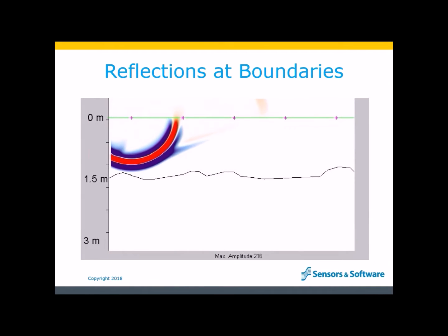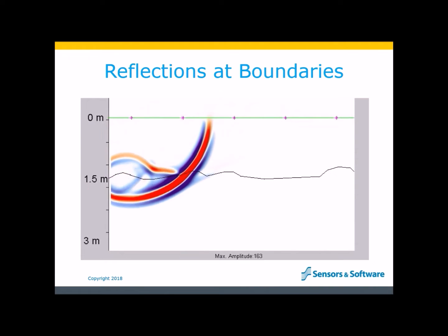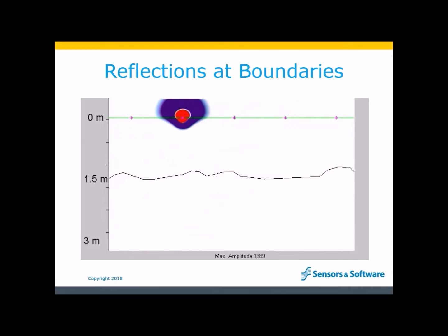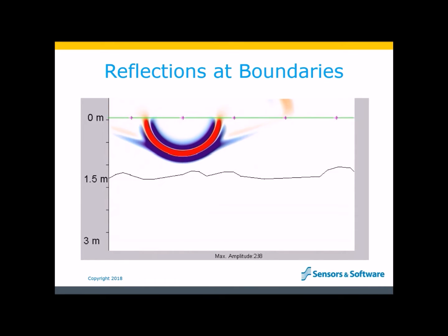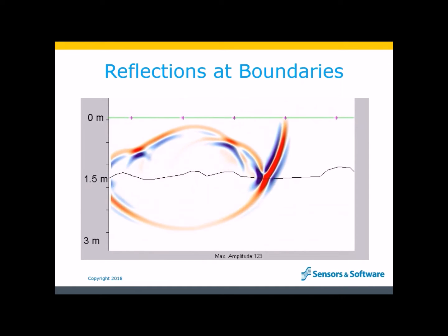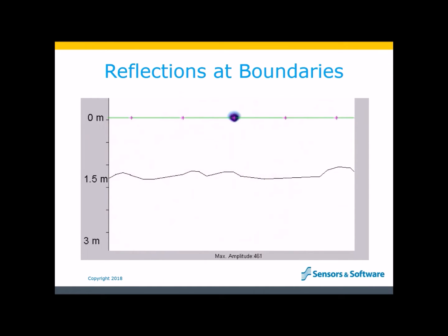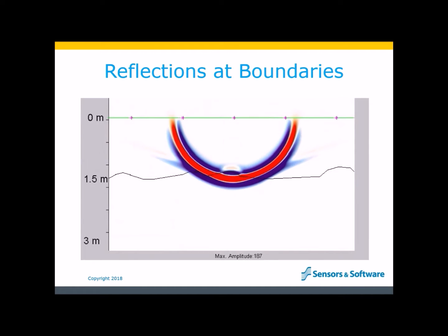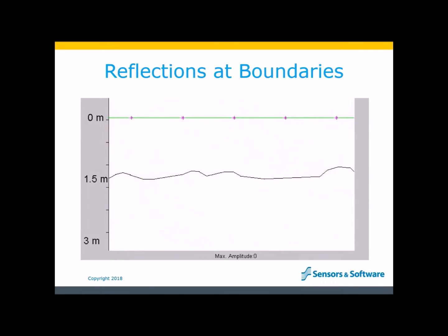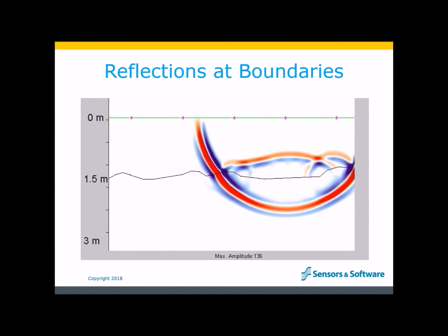Here's another animation that shows the concept of what happens when a GPR pulse is sent into the subsurface and reflects from a boundary between two contrasting layers. It is interesting to watch this for several reasons. One reason is the complex shape of the reflection, even from a relatively simple interface. Imagine how complex it can get if the surface was rougher and the layers were full of objects that caused other reflections.